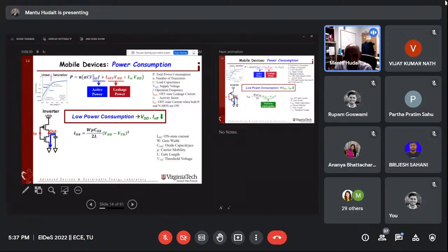It's like on current in a transistor. What is the transistor giving you? The current. That's the most important part, one of the benchmarking parameters. That must be high. How can I make it high? It goes as (VDD minus VTH) squared. If I reduce that, for example, 0.6 squared versus 1 squared, my Ion current has really decreased. So I cannot have that. So they need to be scaled together.